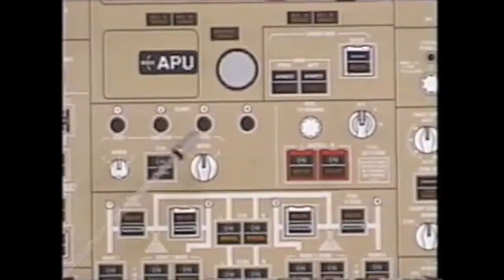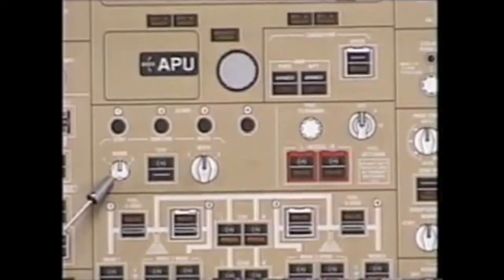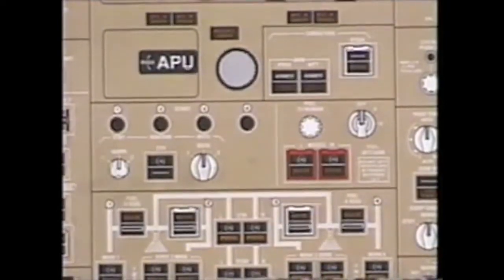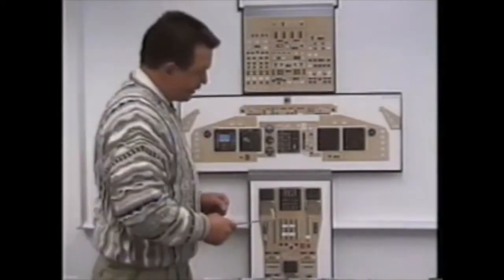Any of the 4 conditions will fire this selected igniter. Standby ignition: normal SOP is to leave this switch in the normal position. In the unlikely event of a loss of all generators, the number 1 igniter on all 4 engines would fire using the backup power supply of DC.